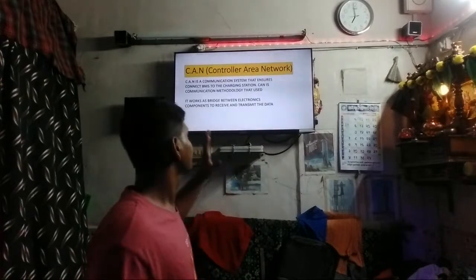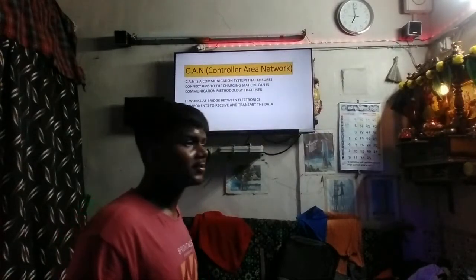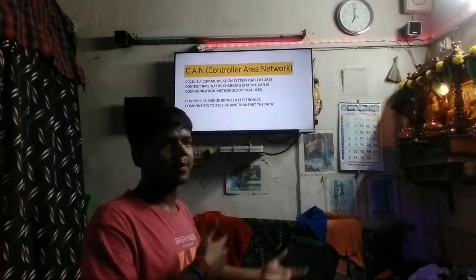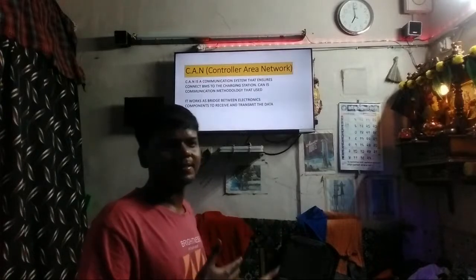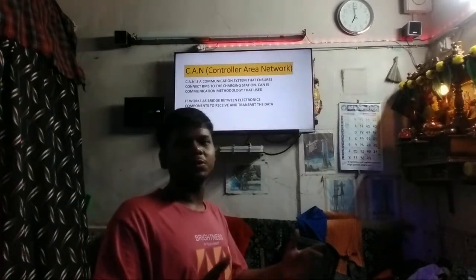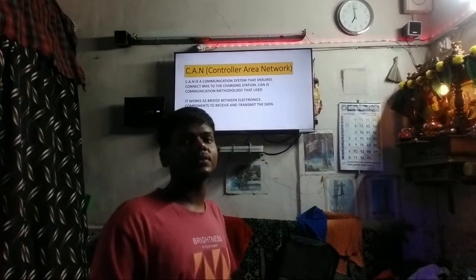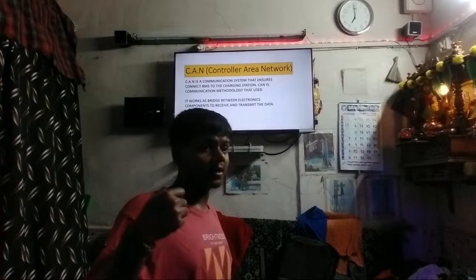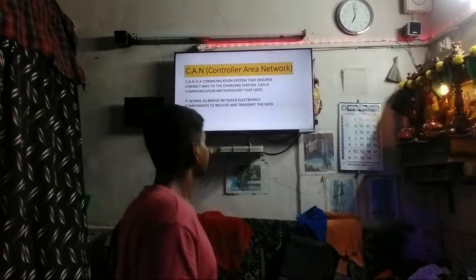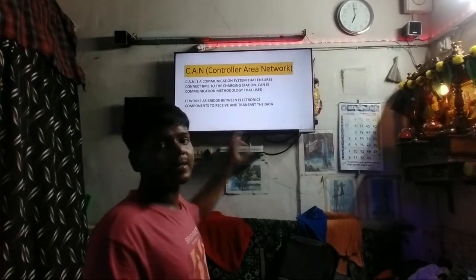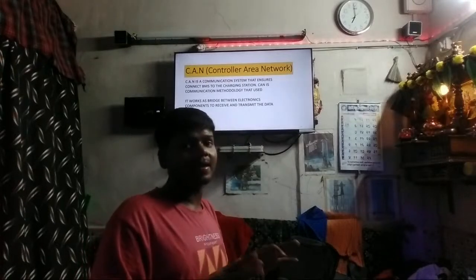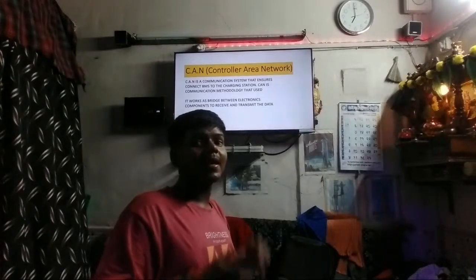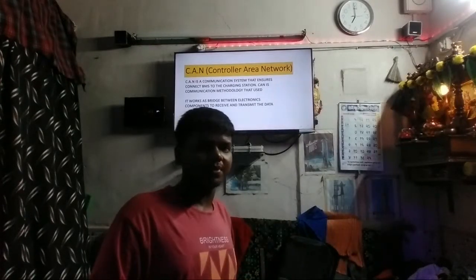Also, it comes to charging your vehicle by using local charging systems. So charging stations that have been created locally, just like a company has established them in any area. So these are the charging stations. When you plug the charging station cable and entire cord into the vehicle, then the CAN can also act as a bridge between the BMS and your charging station, right?